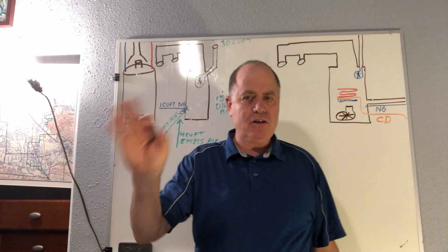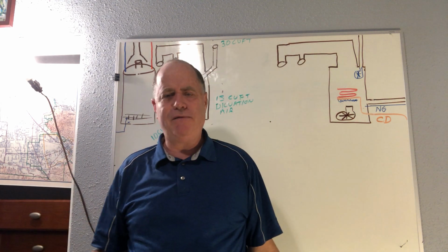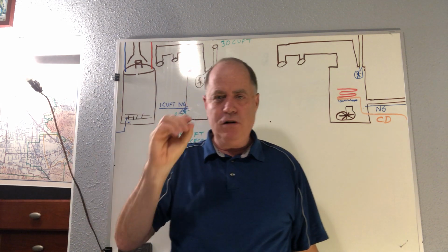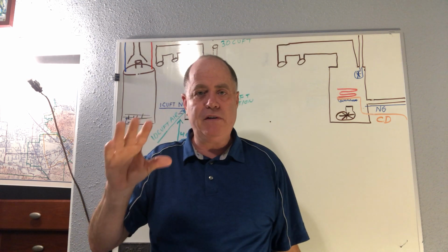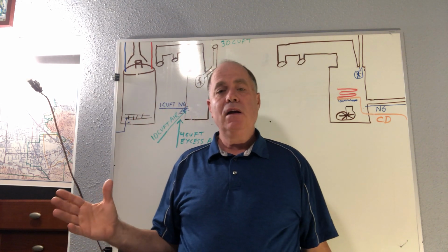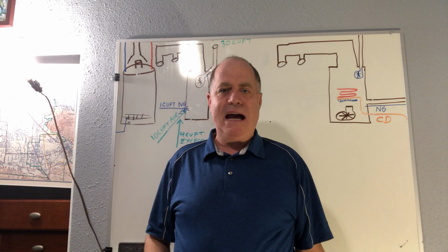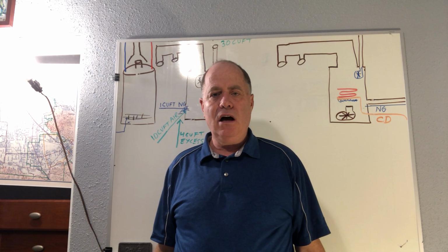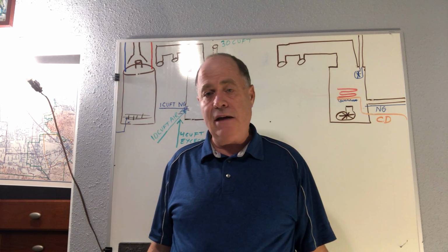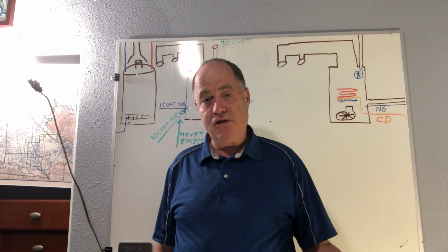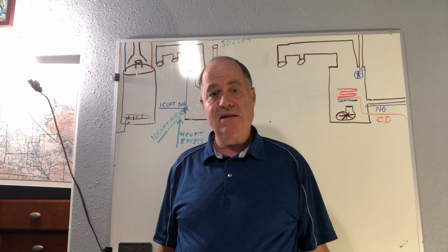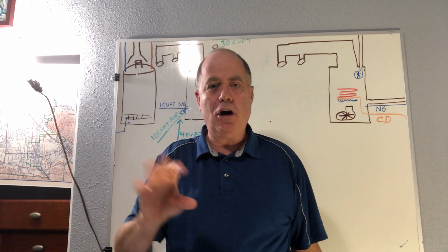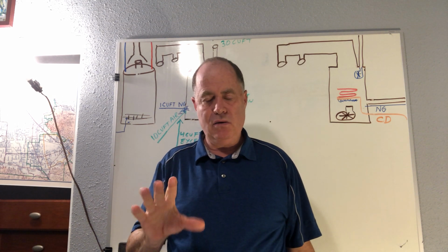When you have perfect combustion, which is really, really difficult to attain, which can be proved by testing, it's possible, a beautiful, perfect blue flame, but then you'd have to prove it. Perfect combustion, which is a perfect mixture of oxygen, air necessarily, and natural gas, like 10% natural gas, 90% air, produces no carbon monoxide. None, okay?